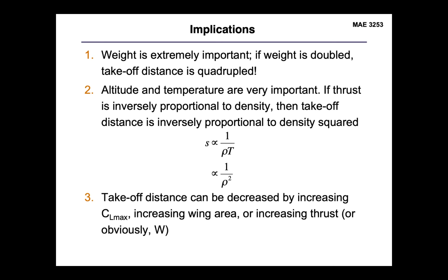Small increases in takeoff weight are going to have a nonlinear impact on our overall takeoff distance. So we have to be very cognizant of that fact when we're going through the design process.